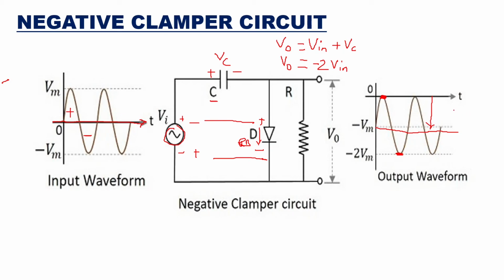You can also have this output voltage like this, or you can also have this output voltage like this with respect to the DC line here, and that can happen if you put a voltage here. So here if you take a voltage in this portion, you can put a positive bias or you can put a negative bias, and it can be called negative biased clamping.